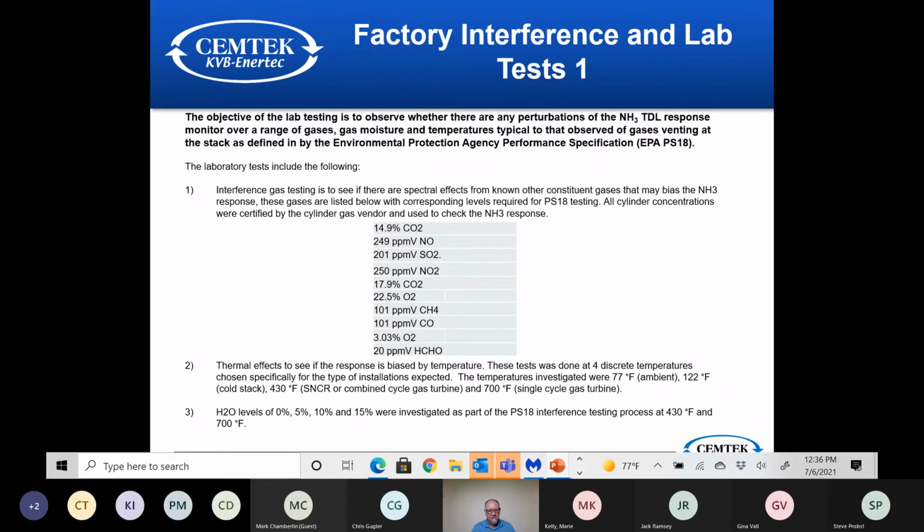And we can achieve that by that very fine tuning of the laser power and temperature and keeping it tightly controlled. So he has the advantage of having the laser down on the ground or in a climate controlled environment with air conditioning, where that laser is at a very specific temperature and the flow through cell is at a very controlled temperature. Some of the other TDL manufacturers have their laser up on the stack in the optics box on the port, and when the sun shines on it, it can get overheated or the temperature goes up, and that can affect your reading. Ours, that's not the way at all.